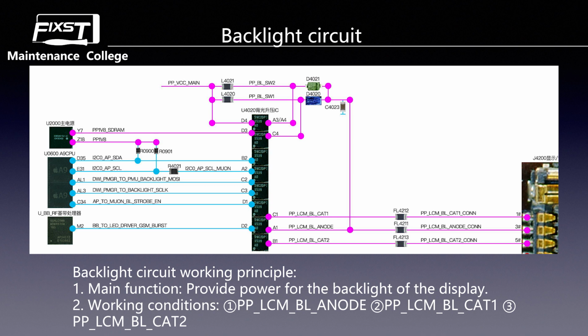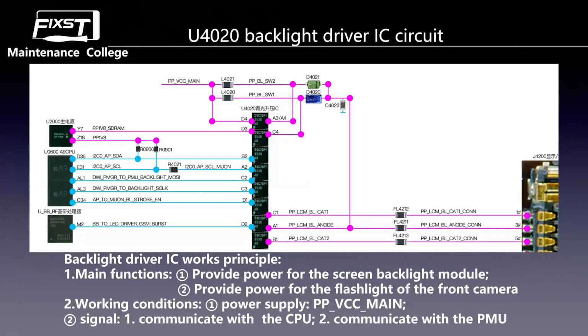The IC U4020, the backlight booster IC, needs to work normally, alright? Because this IC gives the power to it. So we continue to focus on this IC, how it's working, how is it possible. And we have been talking before the U4020, the backlight driver IC, booster IC, his main function is to give the power to the backlight.